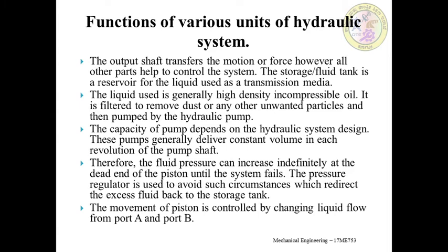Then coming to this, the output system transfers the motion or the force, and all the parts help to control the system. The storage tank is a reservoir for the liquid used as a transmission medium. Previously I told that the liquid generally used is a high density incompressible oil. It passes through a filter to remove dust or any other unwanted particles, and then is pumped by the hydraulic pump.